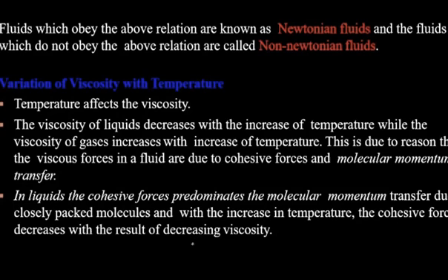Just remember three points. The temperature surely affects the viscosity; the viscosity of a liquid decreases with increase of temperature, while in gases it increases with increase of temperature. Why? Because of cohesive force and molecular momentum transfer. This point is enough for you.